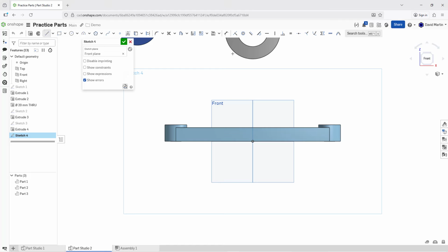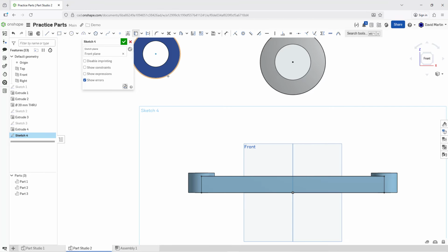I will click on, oh, it's not grabbing on there. Actually, let me grab some other additional things to snap into. Let's use the project command. I will grab the cylinder and this top surface. I also know that I'm going to need the bottom surface later on, so let me grab that as well. Actually, I also know that I'm going to need the cylinder over here for the side web, so I will click on it as well. So now I have grabbed four different entities. I have projected two lines and two cylinders.